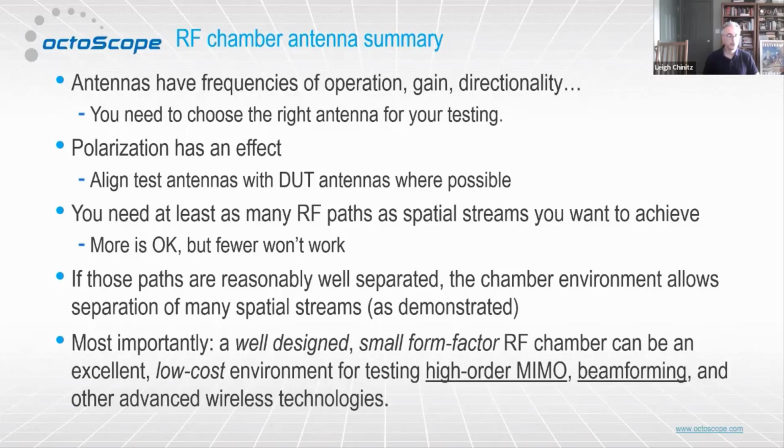We have heard that you get better OFDMA performance, for example, when the devices being used have similar received signal levels, and so at that level, it might be important to make sure that your devices have similar RF paths.